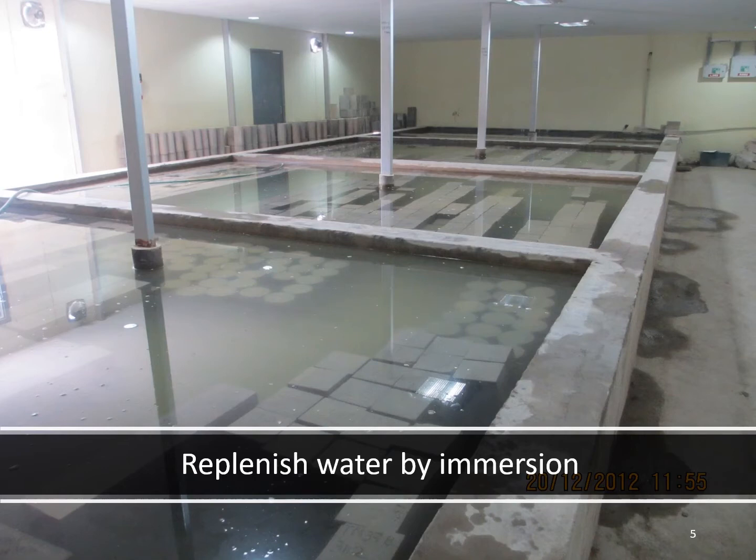Sometimes the immersion methodology is also used for precast units, for example the manufacturing of spun pipes, where the complete pipes are immersed in a curing tank for 7 days or 14 days depending upon the requirement.